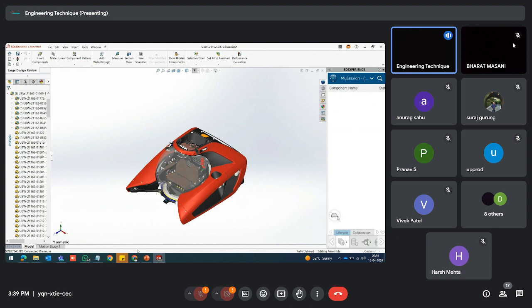As you have seen through this session, while using the LDR mode, you can optimize the large design settings. You can optimize your performance in large assemblies by using this LDR mode. You can't use some features in it, but likewise you can also use the lightweight mode for some of the settings in it.